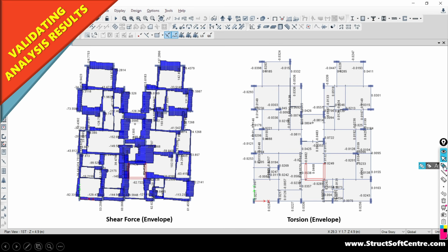At every section you will get two shear force values. You need to see what the torsion is, whether the torsion has developed or not, whether you want to consider the torsion for the beam, or would you like to release the torsion, whether the torsion has been released or not, how you can ensure that, how you can interpret that, that also we are going to see in detail.